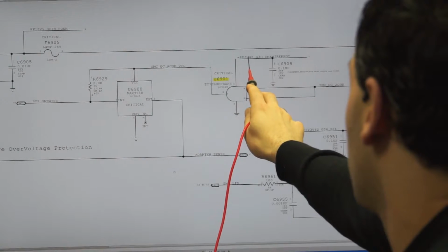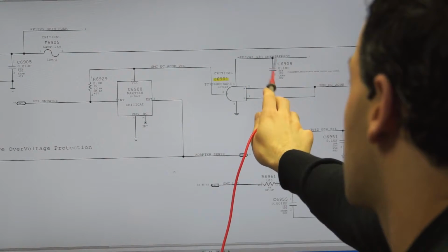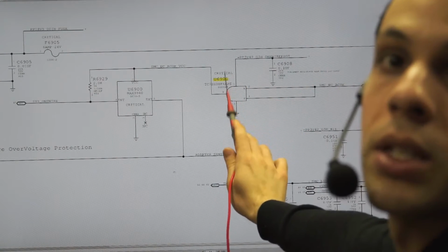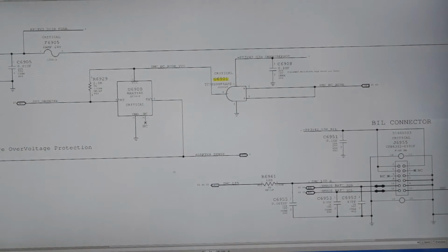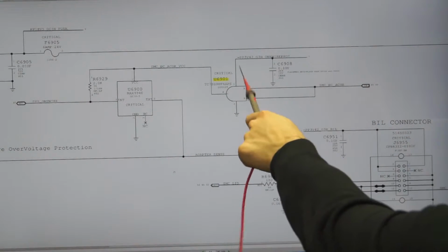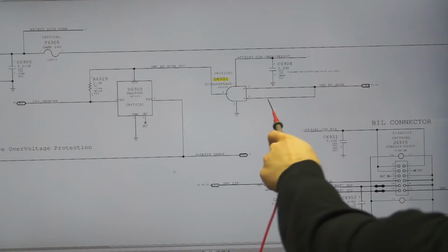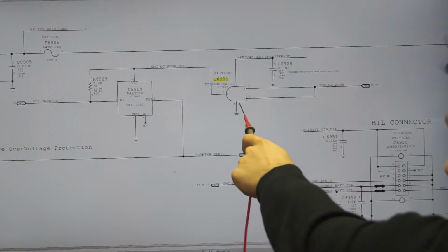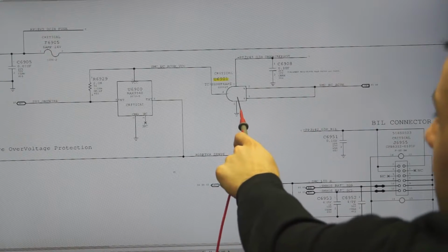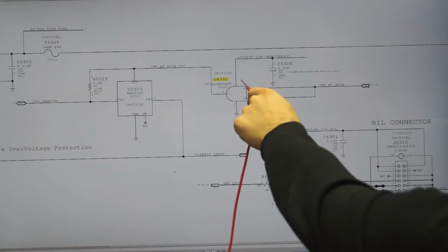So over here you have PP3V42_G3H. This is the main power rail connecting over here. This is a very, very common via to corrode. Also, it very often takes this chip out with it. So if you see SMC_BC_ACOK coming in here, but it's not coming out on pin 4, check this power line.